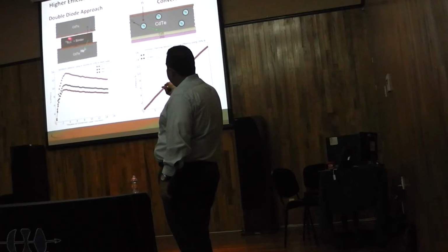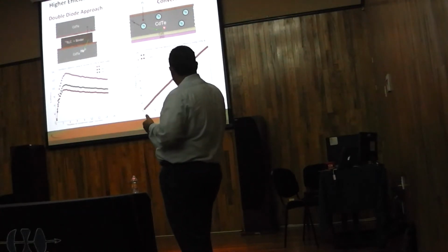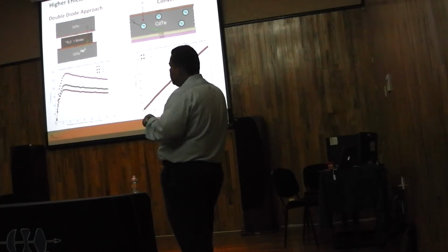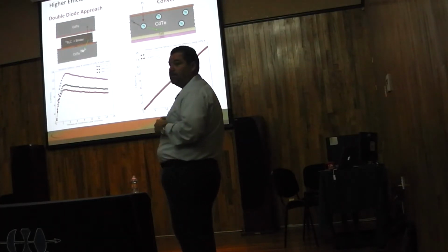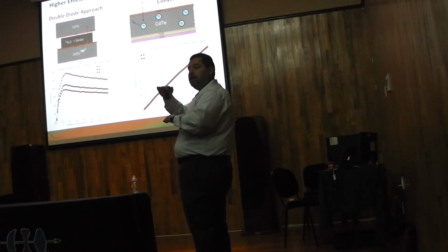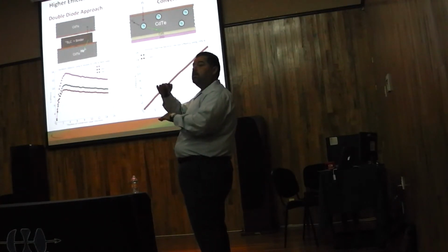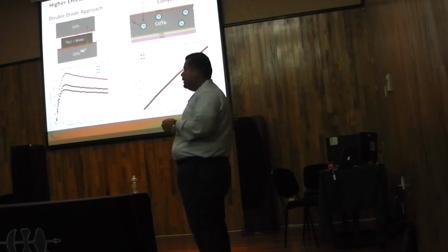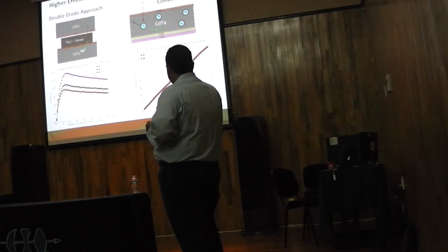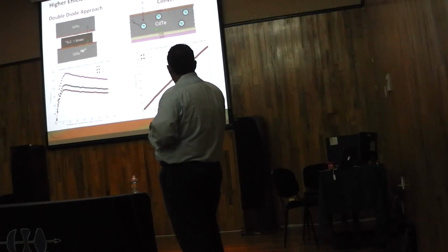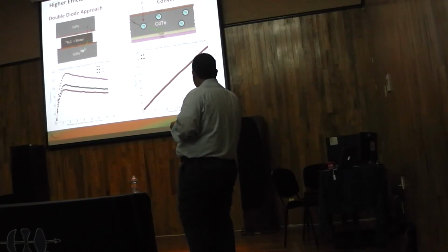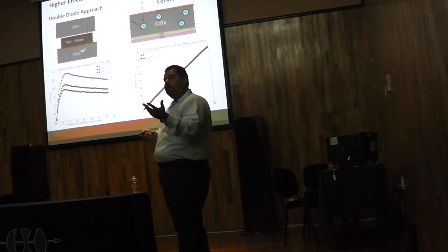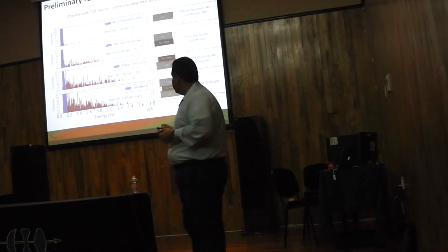So this is putting the converting layer outside the diode. I can also put the converting material inside the diode. The problem then is that to get to 13% efficiency, I need to have a diode that is as thick as 25 microns. So a very thick diode, and that means the diode will need to be run at really high voltage to have a really wide depletion width. So this might not be a good way to do it, but this has only 20% boron inside. So if we go to 40% boron, we'll go from 25 to about 12.5 microns. But if I put more boron, I may create more defects in the diode.